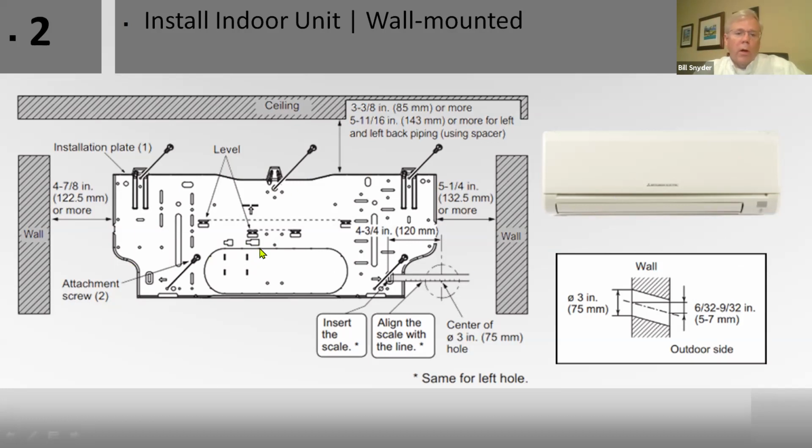And then when you hang this unit on, everything will line up. So you're not trying to hang the unit out of the way, make your flares, see if they line up, put it back. This will be the exact same spot. You can take the styrofoam that comes as a shipping thing on each end and hang this on and shove that underneath to hold it away from the wall so you can get in there and make your flare.